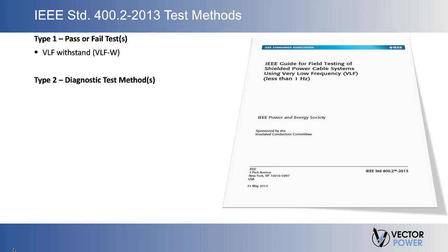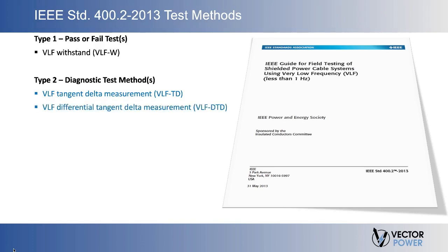Now, IEEE standard 400 also talks about type 2 tests, which are diagnostic in nature. Tests that are diagnostic in nature would be the VLF tan delta measurement, or the VLF differential tan delta measurement, or the VLF tan delta temporal stability measurement. These are all described in the IEEE 400.2 document.